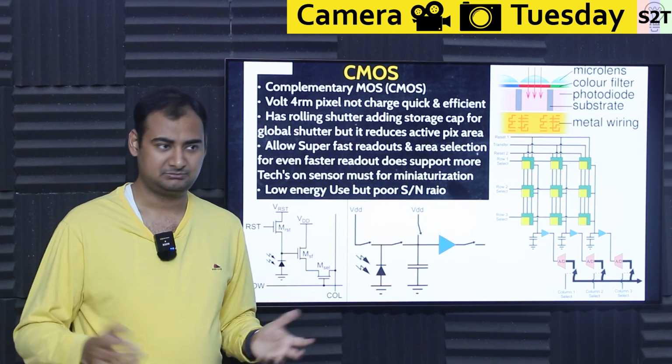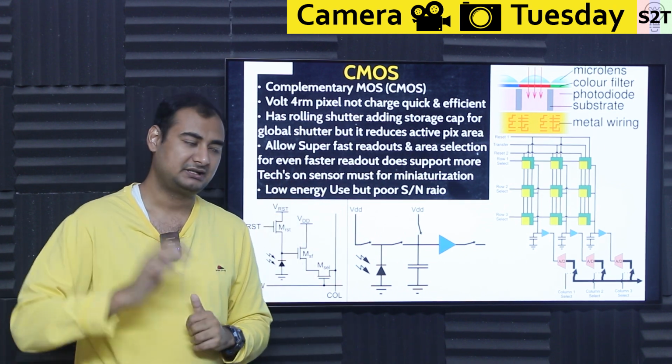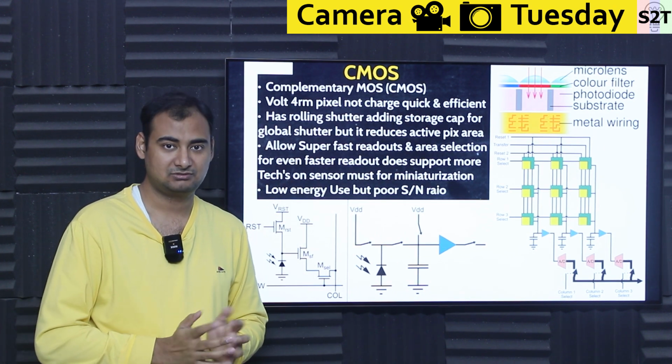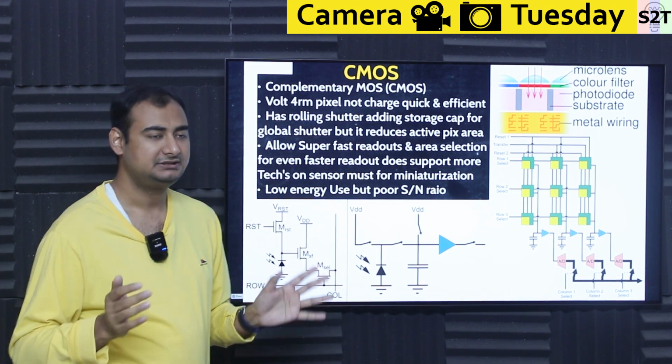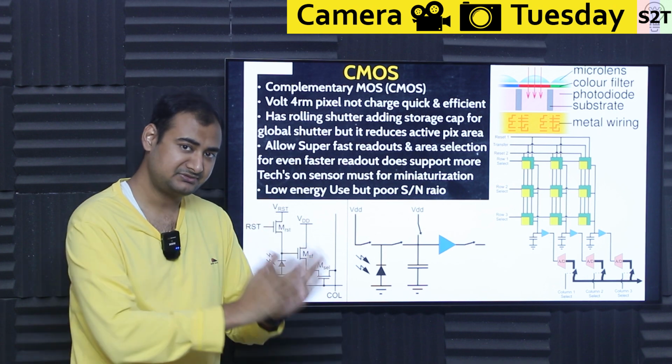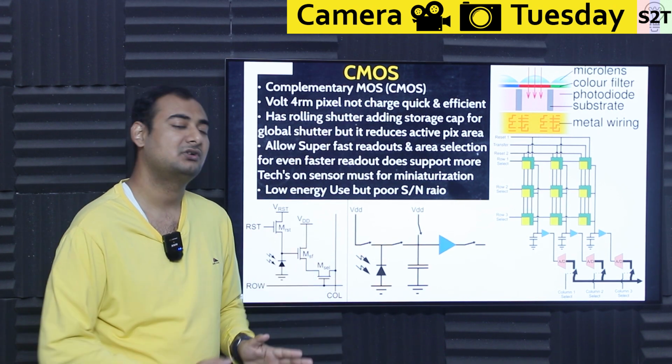So if you go to Sony and say, hey, this is the sensor size, I need a global shutter one, I need one non-global shutter, rolling shutter, and both could be monochromatic if you want absolute signal quality, they're like, awesome, but here's the deal. Sony themselves will tell you, if you choose global shutter, it will give you at best 14 stops of dynamic range.